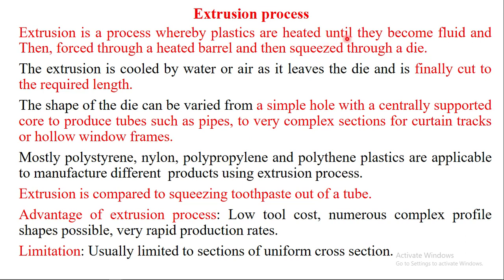The plastic materials are converted into melted or fluid materials below 260 degrees centigrade. So until they become a fluid, then they are forced, heated, and squeezed through the dies.